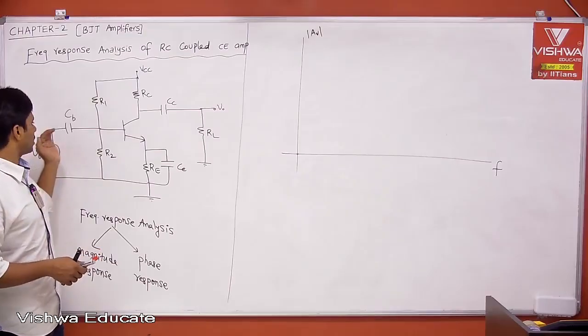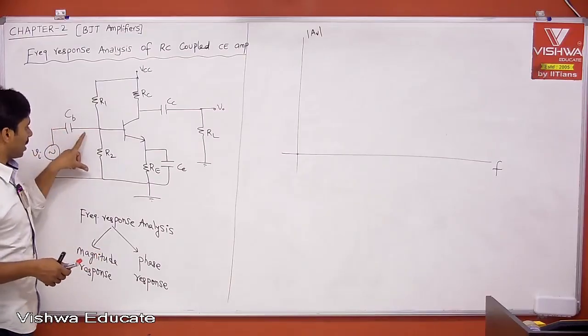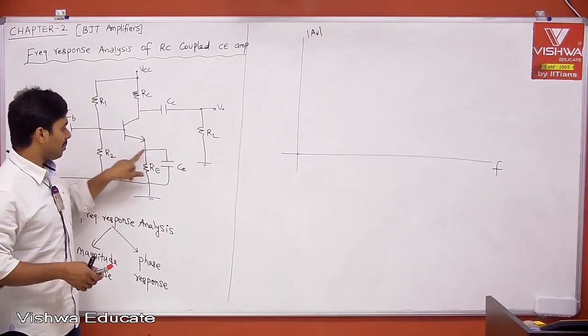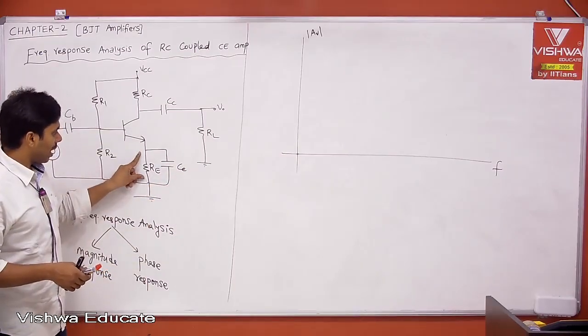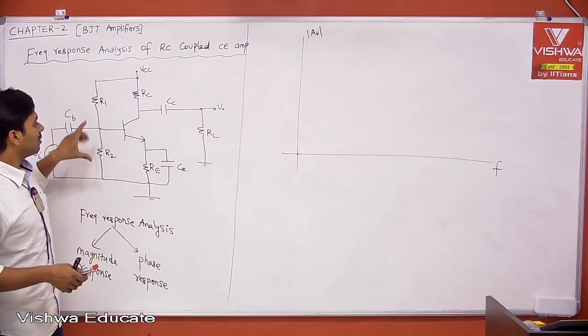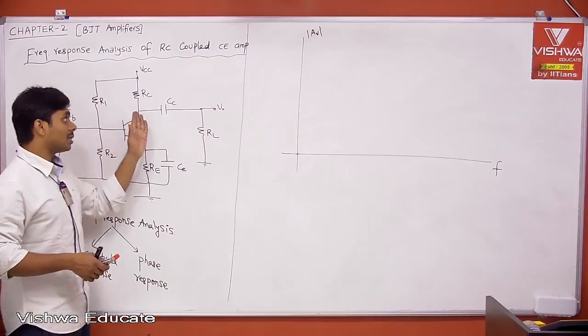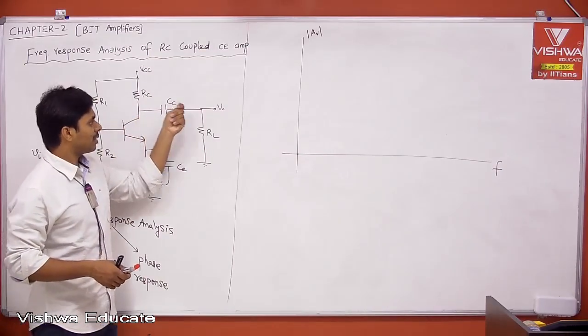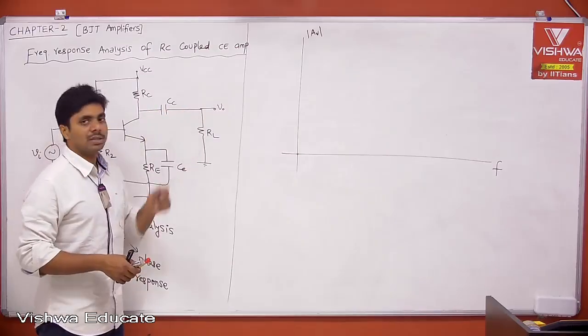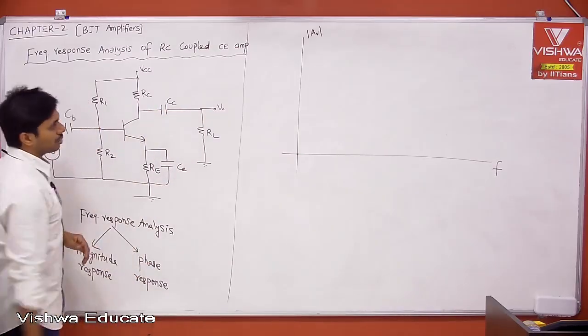Even though a partial signal is going, let us say 1% of VI is applied here, then that too is with maximum negative feedback, because this is almost open circuit, with minimum gain. Whatever signal you get after minimum gain will be passed from here to here, let us say 1% of this, therefore I can say almost zero.